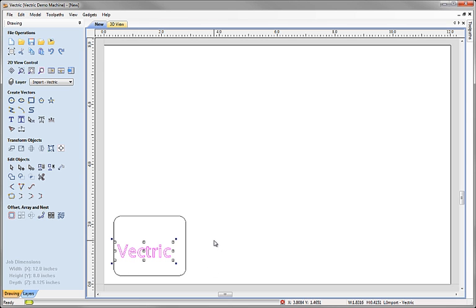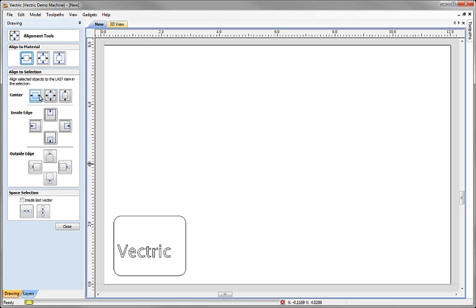I'll take the opportunity to show you the layout alignment tool here, which is quite handy for this sort of job. With the alignment tool, we can align things very precisely, either in the middle of an object or to their edges. In this case, I want to align it to the middle in X inside this object. So if I select the thing I want to align and then hold down the Shift key, I'm also selecting the thing to which I'm going to align it.